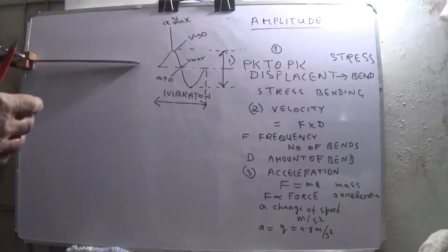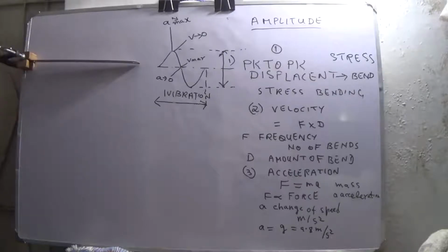When the condition is not good, naturally you will want to find out why there is more vibration, and you should know the fault, because if there is more vibration, the machine is going to break up. You can also balance the machine by means of vibration analysis.